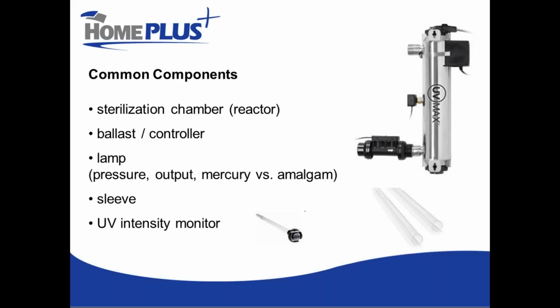They do not have the same coatings on them for UV transmissivity. So you are not assured of the same level of dosage. And in extreme cases, we've even seen situations where the lamp pins don't fit properly. They're a little loose. They cause arcing, and have actually had melted lamp harnesses and even ballast and controller damage. So it's not something that you want to take any chances with.